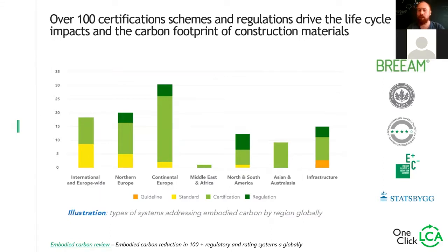We have guidelines, we have certifications, and we have regulation. While certifications are great, they are usually optional. So you don't necessarily have to do them. But if we have regulations, then people have to do building LCA, or they have to do carbon studies. When we take a look at the biggest ones around the world, for example, BREEAM and LEED, these are sometimes demanded by, for example, investors, that they have to have these kinds of LCA studies done before the building is actually constructed. In Finland, we'll have the YM method, which will become mandatory. And in France, we have the Energy Carbone and the RE 2020. In Norway, it's also mandated by Statsbygg, one of the governmental real estate organizations, to do assessments for NS 3720, the Norwegian standard.